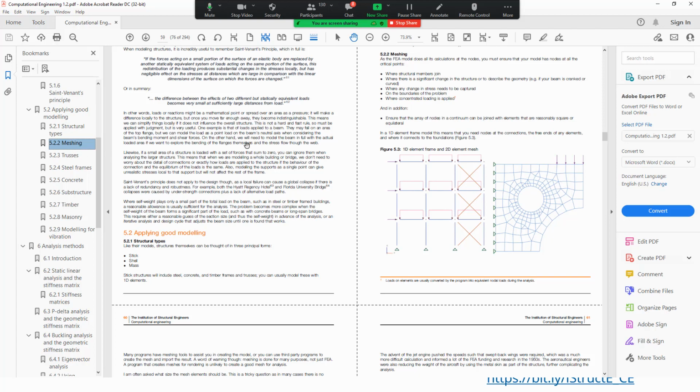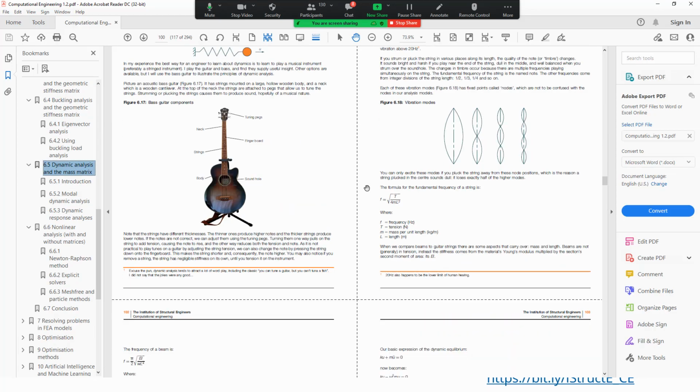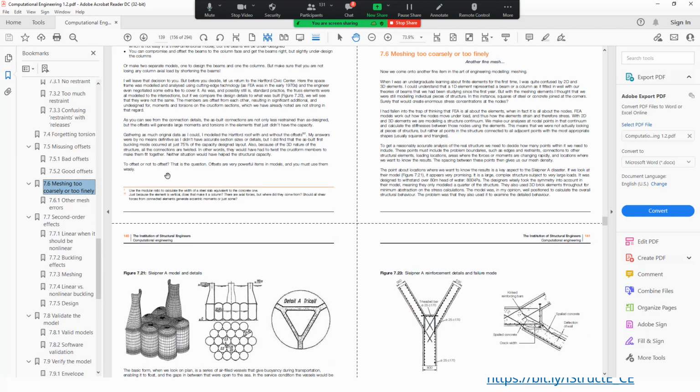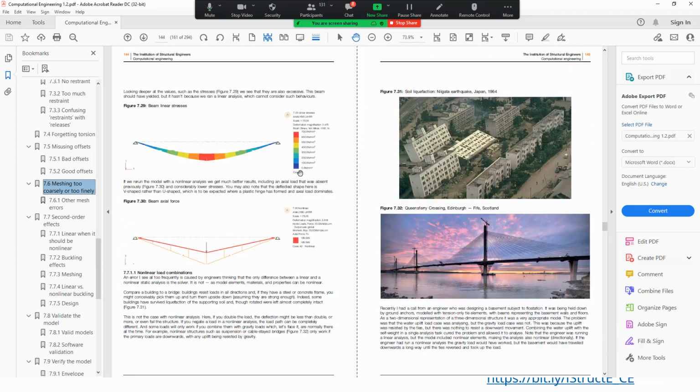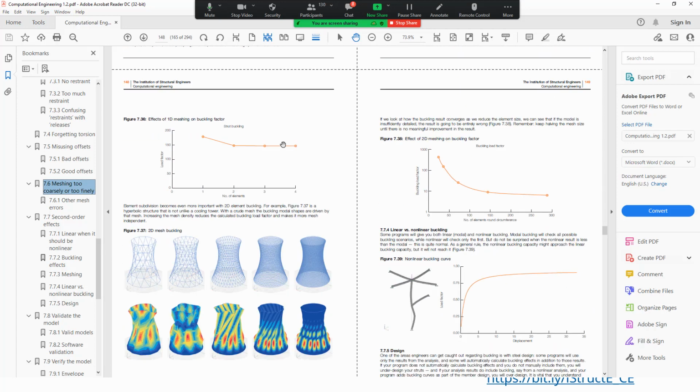Likewise, also buckling and dynamics, which I cover in here somewhere. Maybe it's in the errors section. Yes, so with buckling and dynamic analyses, you will find as the mesh size reduces, the results will change and they will usually level off. So you've got to make sure that you mesh fine enough to actually get the results you're looking for. The general rule: keep halving the mesh size until the results don't improve anymore, or you hit the twice thickness limit, and that's probably close enough.